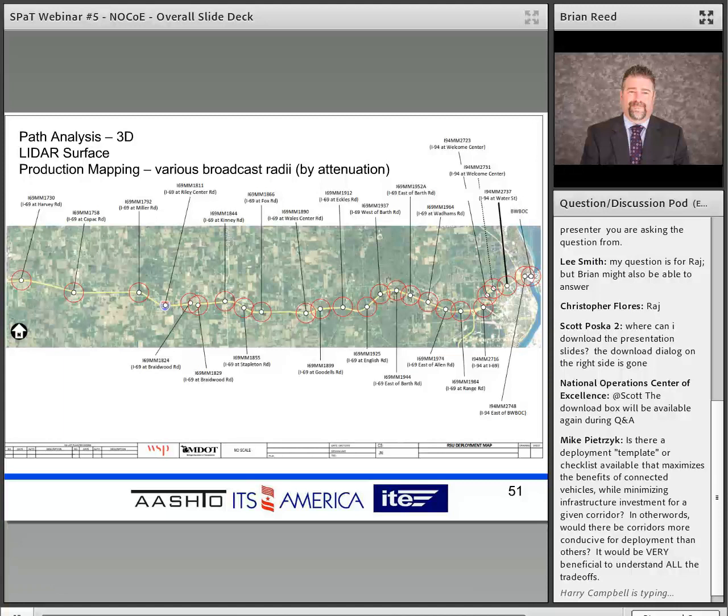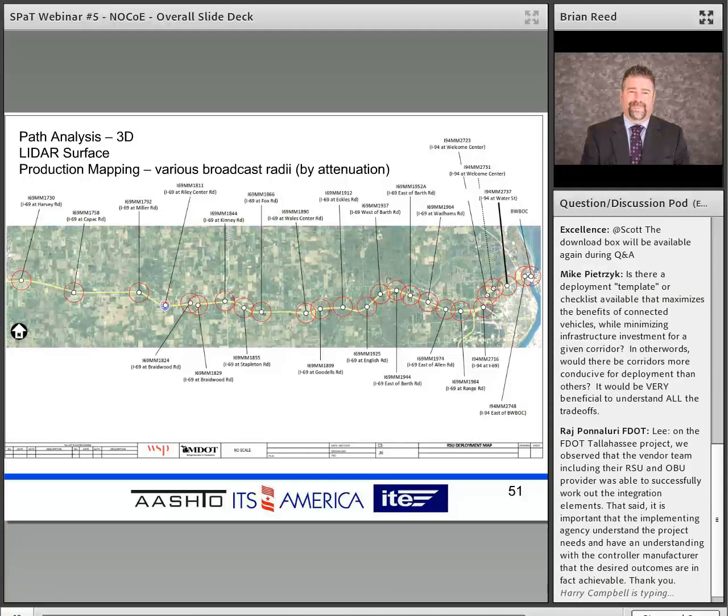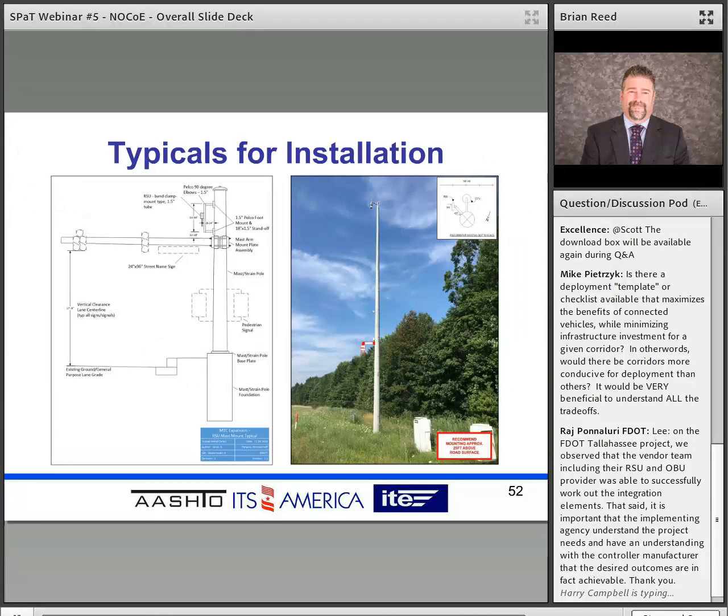Certainly if there's an intersection that is a safety critical location that has high accidents or a lot of vulnerable road user usage, those would definitely be what I would call critical drivers to installing an RSU in those site locations. Out along the freeways, to broaden out the coverage area, it helps to have those RSUs spread out. And then when you're looking at data aggregation and bringing that back for analysis, it helps you have a broader implementation through a corridor or a location set.